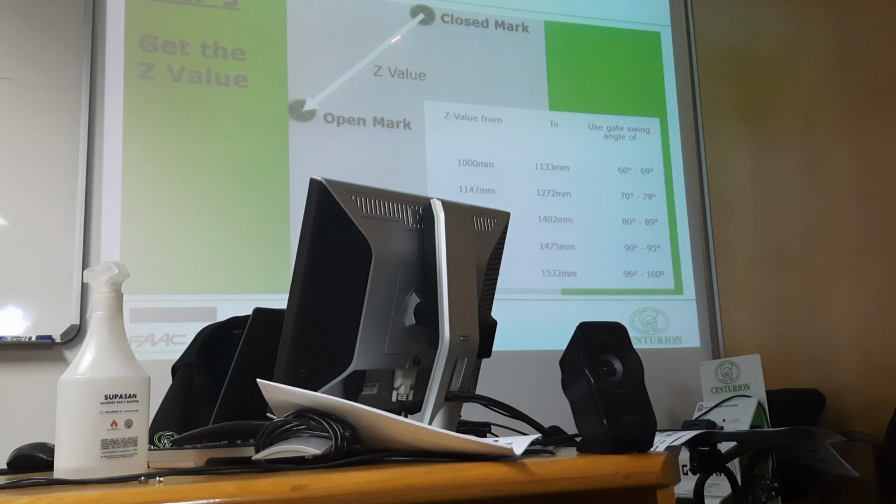So it's purely the length between that X and that X, because your gate is now obviously, there's your pillar, your gate, there was your closing angle, there was your opening angle, and then that's your length. And that length will tell you if I'm running between 1 meter to 1.1 meters, I will have only up to a 69 degree opening angle. If the client insists he wants a 90 degree opening gate, then this value must be at least 1.41 meters. Okay.